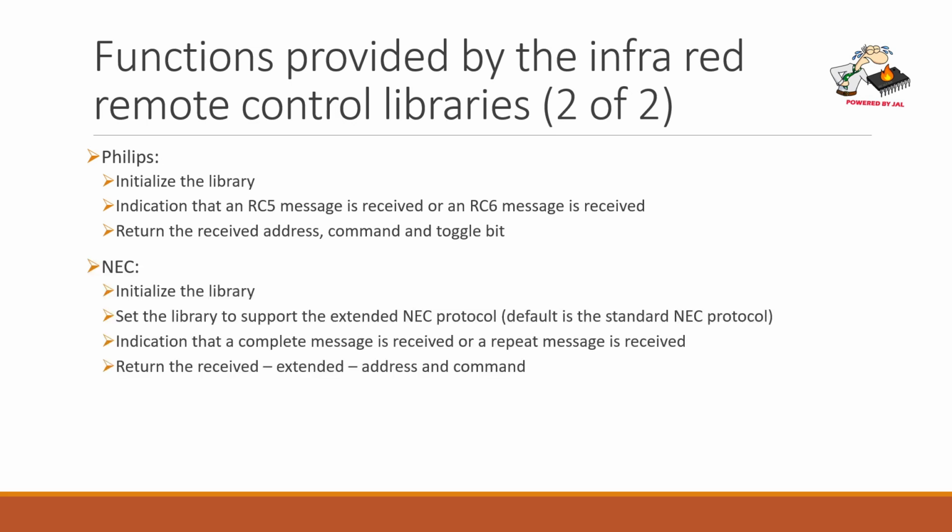The next system is almost the same. You initialize the library, enabling the interrupts. Then you can set the library to support the extended NEC protocol, because the default is a standard NEC protocol. It will indicate when a message is received, or when a repeat message is received. And it will return the received address or the extended address, and the command.